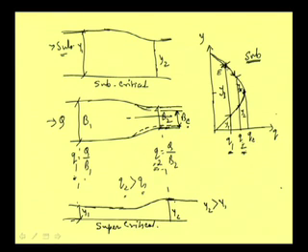As you can see, Q is increasing. And then for a particular B value, this Q will become QC. That means we are arriving at this point. Depth is coming down and coming down, and we are getting a depth which is the critical depth. This is our YC. So, we can reduce it up to a particular B value, so that we can get a critical depth here.